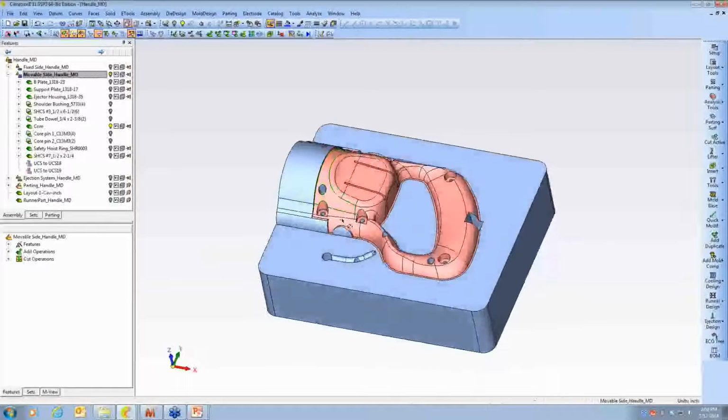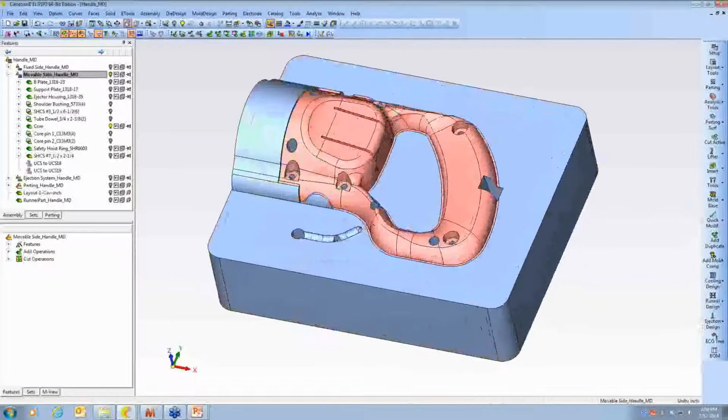So in a mold of this type, the core block is typically the only component in the B side of the tool, which is what we're looking at, that would receive cooling lines. The surrounding plates do get hot, of course. Actually, the overall temperature of the entire mold should cycle up and down in conjunction with the molding cycle. But for tools with individual cavities like here, adding cooling into the plates isn't really a big contributor towards the goal, which is removing the heat from the plastic part.